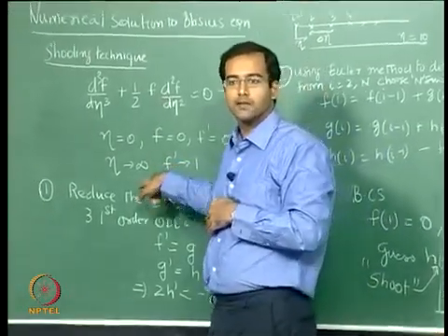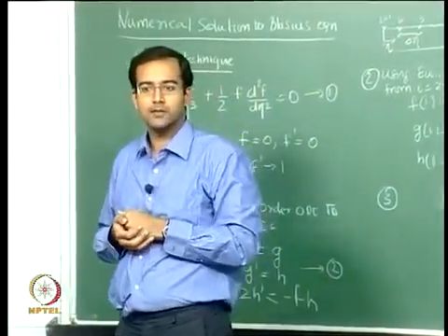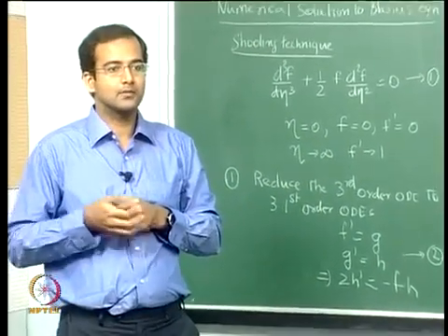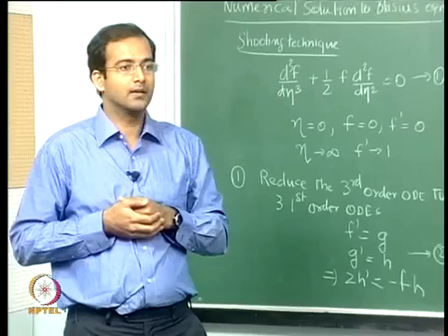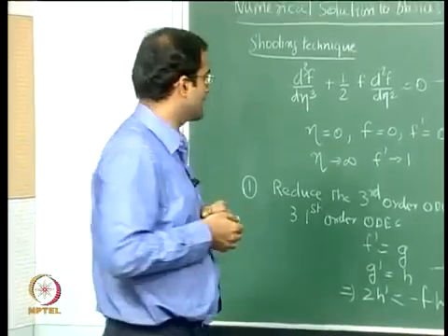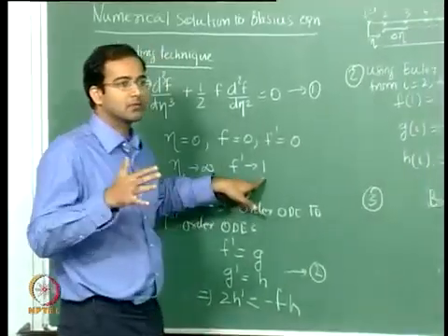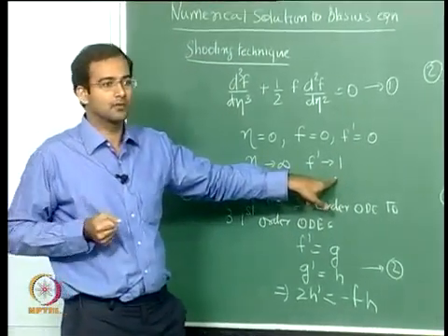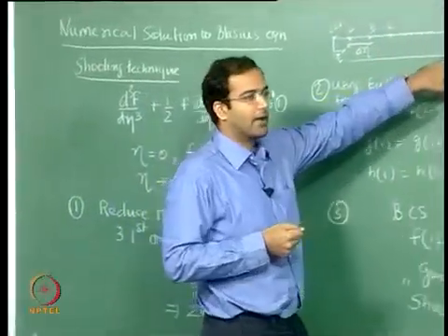We have already seen from the Blasius solution that the boundary layer thickness extends to a value of eta close to 5.58. Beyond that you find that f prime is almost 1 and doesn't change. So anything above 5 or 6 should be good enough. For the safer side, you can take a value of eta up to 10.